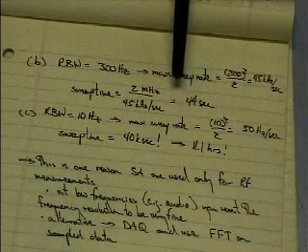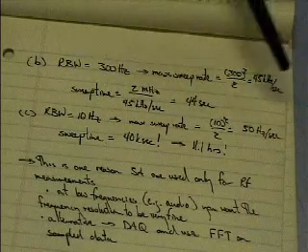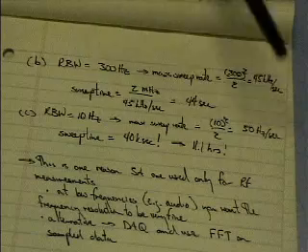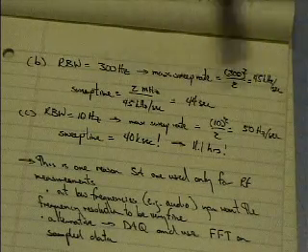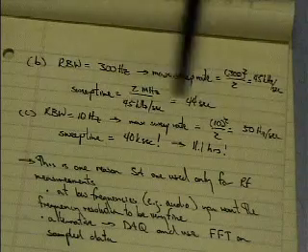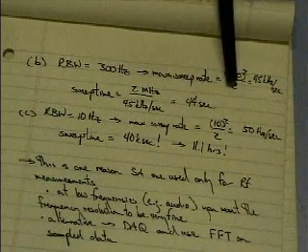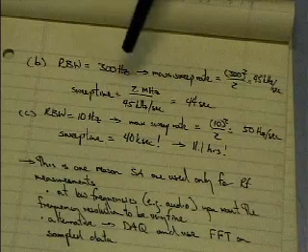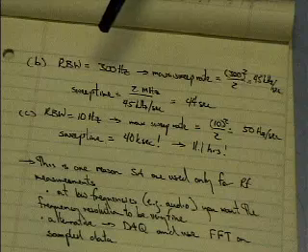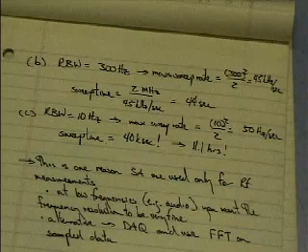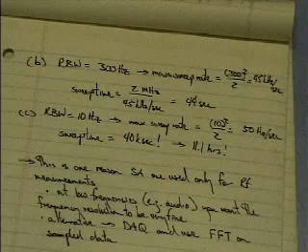We're going to be finding that if we're sweeping across the screen and it takes longer than a second or two, that's going to be a pretty slow measurement. These things are meant to be pretty fast. So for this particular 2 megahertz span, we're probably going to set up the res bandwidth to maybe 10 kilohertz. And as long as we're not trying to identify two signals that are very close together, then we'll be fine.